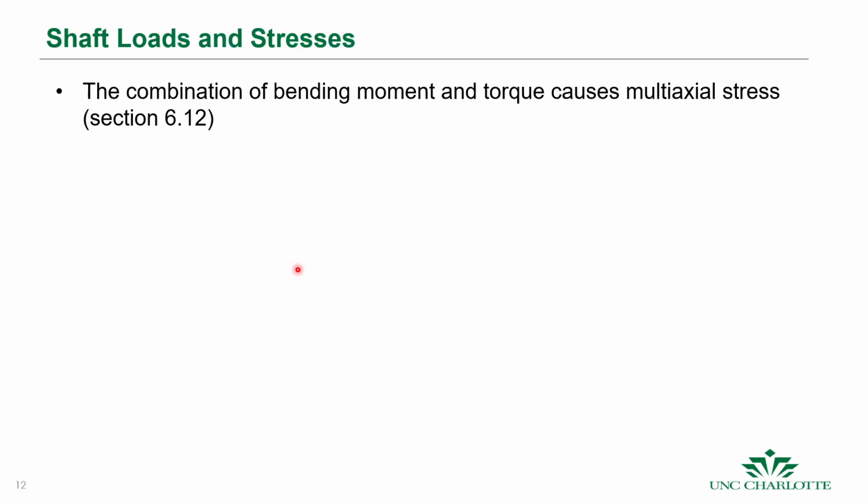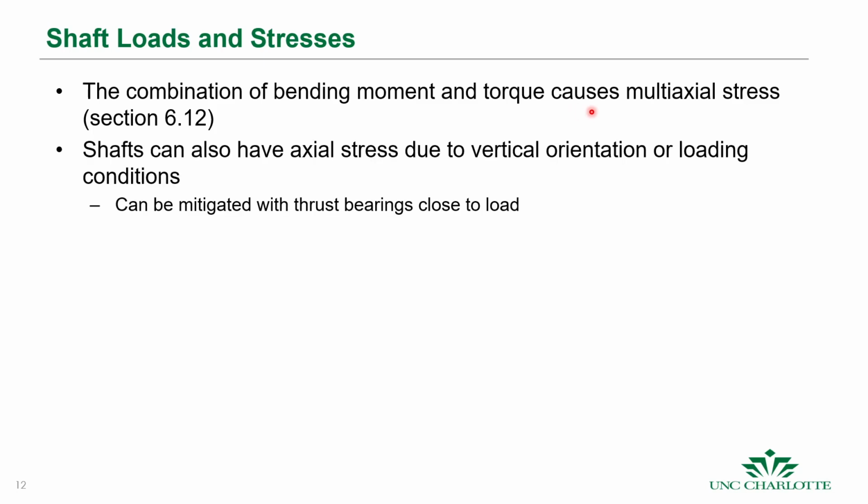Because we often have bending moments caused by transverse loads, and we have torques caused by the applied torques and the reaction torques through the gears and other components, this causes multi-axial stress. So we can apply what we did before to find our effective stresses.